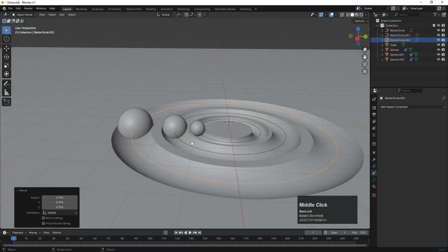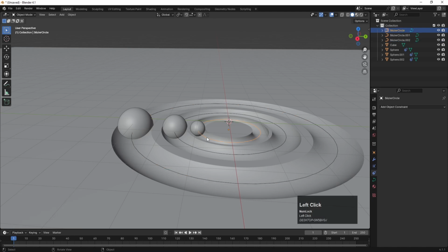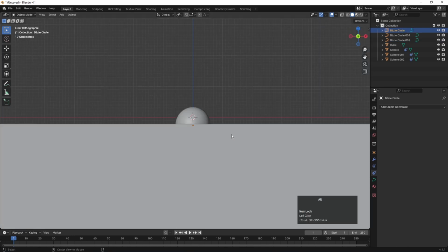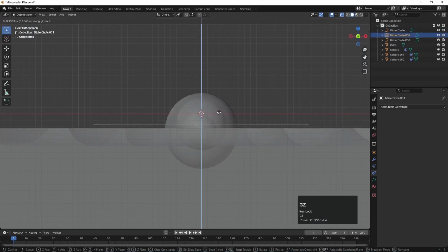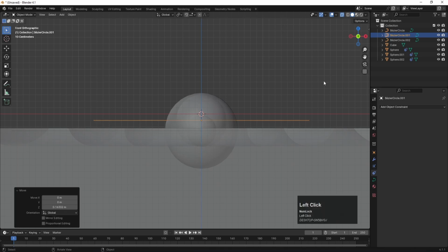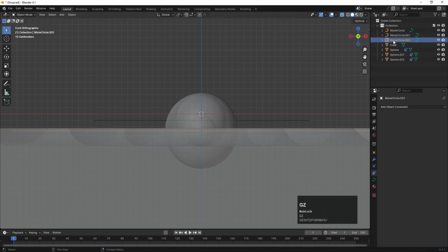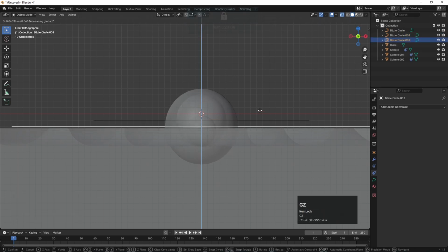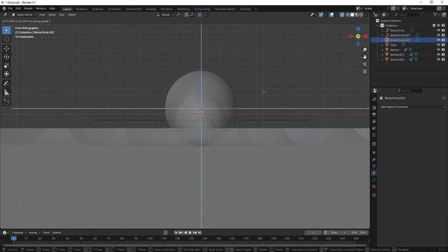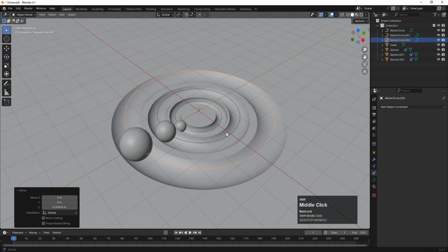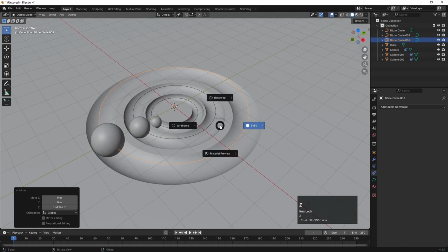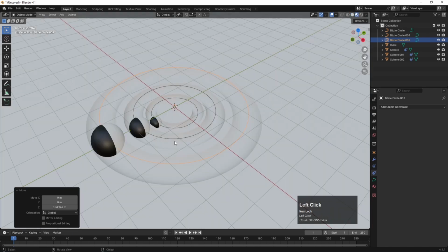Okay, now after that we need to adjust the position of this curve. So let's select this, hold Alt Z. Select this Bezier curve, press GZ and try to bring this in such a way that the bottom should touch this line. Select this, GZ, and try to touch it in a proper way like this. Okay, and hold Alt Z like this. Now if you see this in material preview, we will get something like this.